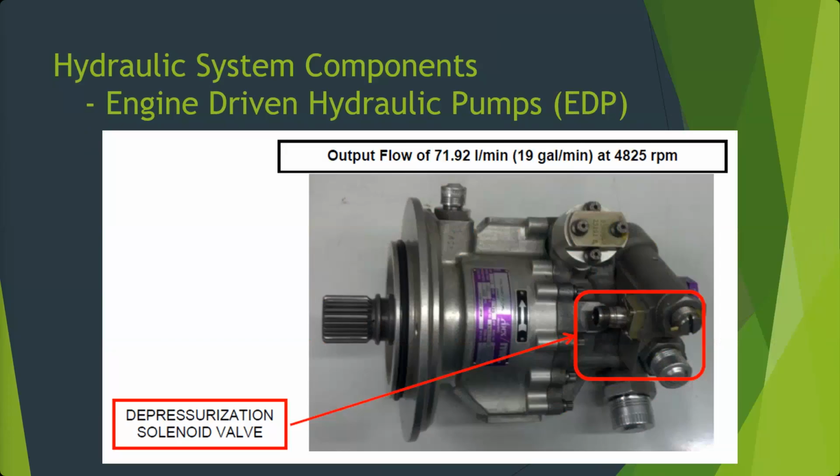So I have this. This is a smaller pump than the one I've got here, 19 gallon per minute flow. You can see it doesn't have a pressure on there, right? They know how much pressure they can rate, but the pump isn't creating pressure. The pump is creating flow. Pushing that flow into an enclosed space is what creates the actual pressure.